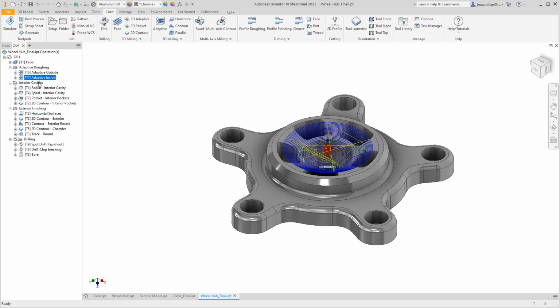And then as I go into these additional toolpaths, you can see I've used a radial and a spiral. These are basically strategies that are going to enable me to machine that interior cavity and get a nice finish on it. You can see here one's radial, one's spiral. It's a little bit tight here, so that's why it's really solid blue. The step over is very small to give it that smoother finish. And the radial and the spiral in two different directions really finish that nicely.